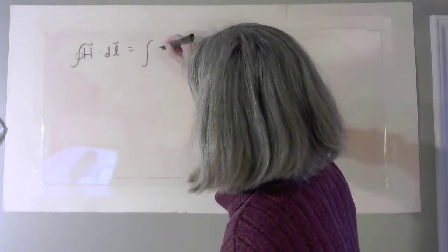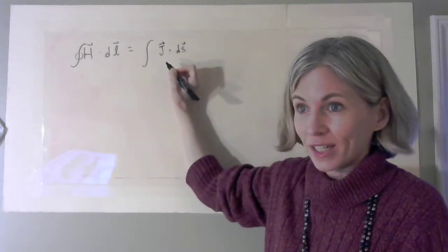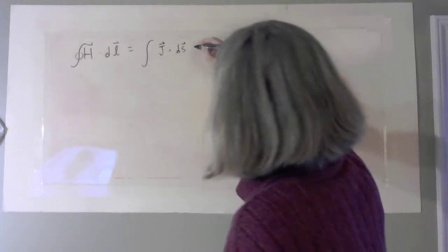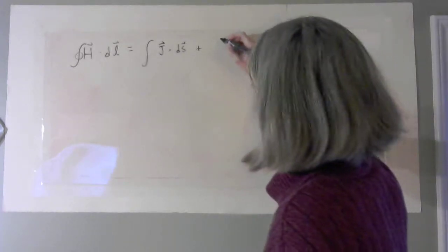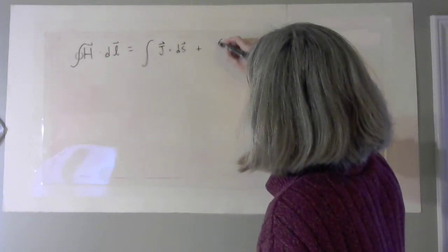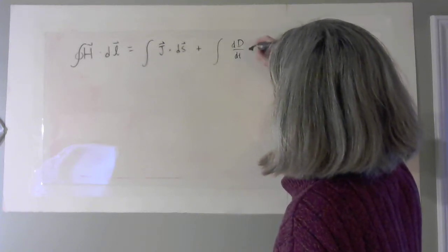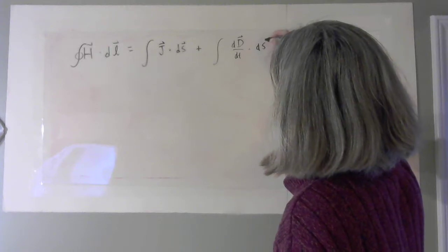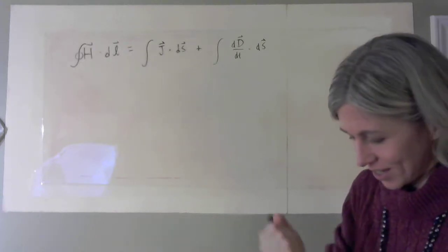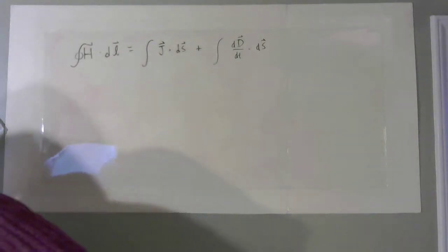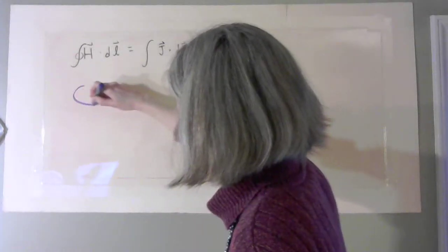This is the surface integral of conduction current density, J, plus this other thing that we learned about last time, displacement current density, integrated over that surface bounded by this path. I'm going to draw this out, and you'll see something interesting: all that matters is that the surface has to be bounded by the path that you're doing this H integral around.